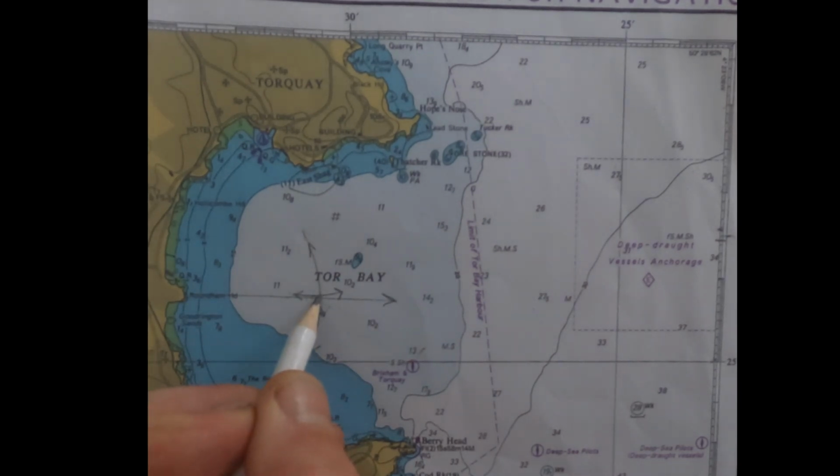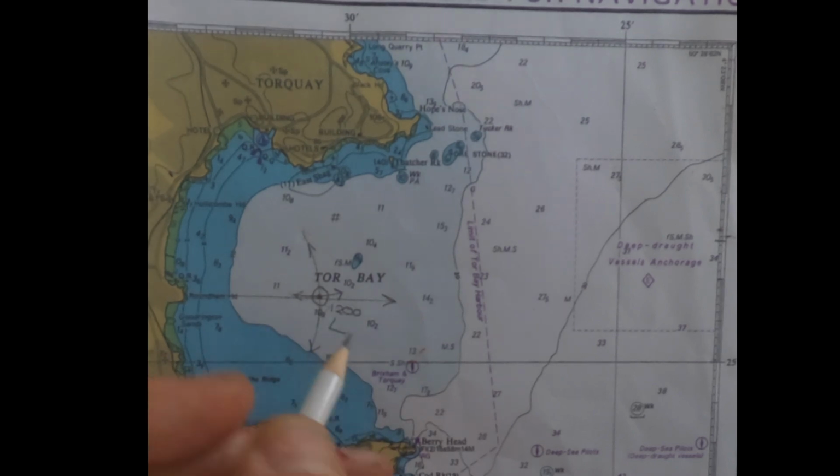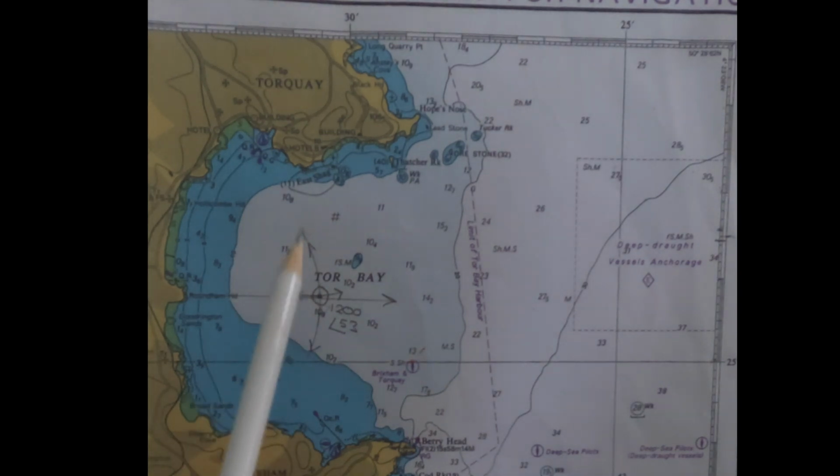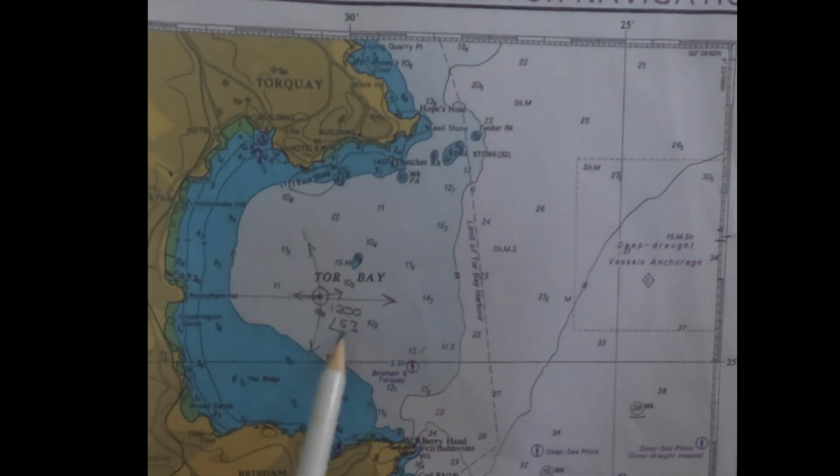Okay, so we think we're in this position. Do a dot and a circle. It's midday, so we're going to put the time at midday. We put an L and put our log reading, which is 53 miles. And then to double check this, we're going to look at this visually. Are we about halfway between East Shag and Brixton Harbour here, and a little bit further out than that from Roundham Head? And we're going to check our depth. So our depth is around 10.5 meters plus the height of tide that we've worked out above chart datum. So we're trying to use all the information we can to back up our position of where we are.